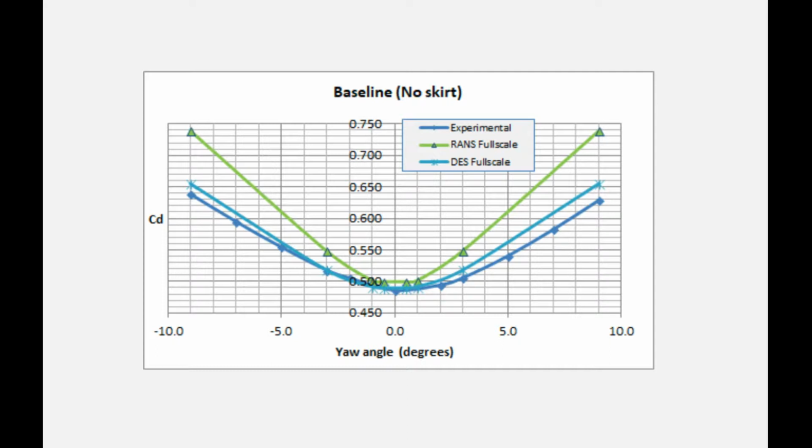Because when you're traveling on the highway, you can expect the wind that the vehicle is facing to be changing in direction. So this is the wind averaged drag coefficient that we recommend trying to accomplish. And we'll provide an example Excel for how to use those points and get the final drag coefficient value.